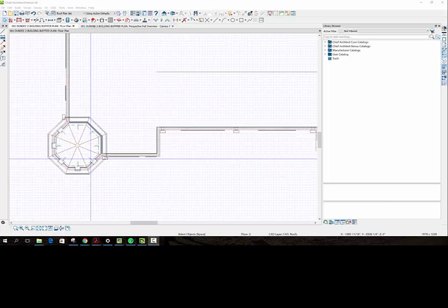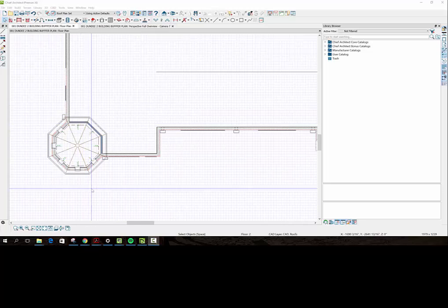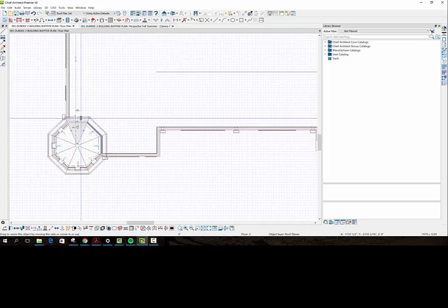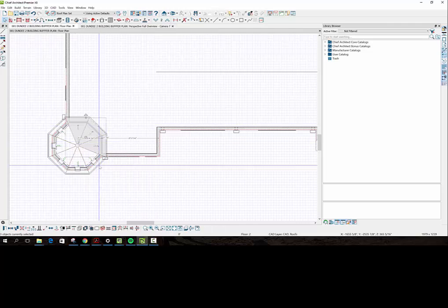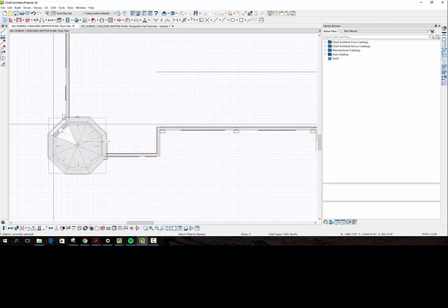And here, when I turned on the roof plan, we'll notice that the gutter line is drawn. Since we do not want to use a gutter, we hit our Shift key, connect all our roof planes, select all our roof planes, hit our box here, and I'm working on two screens.